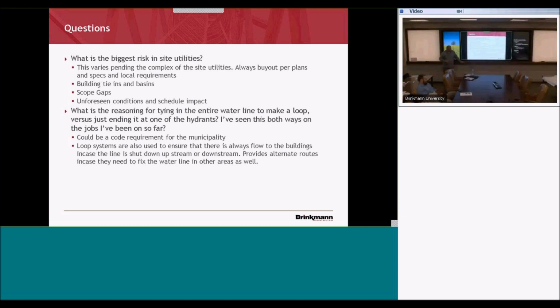And then the last number you want to remember for the engineer's quiz is, what's the maximum number of feet you have to travel for an actual egress, for a ladder? 25 feet. Yeah, winner. 25 feet, there you go. 4 feet for a ladder, no more than 25 feet for egress, 5 feet for benching or shoring. So you've got to have a ladder every 25 feet?